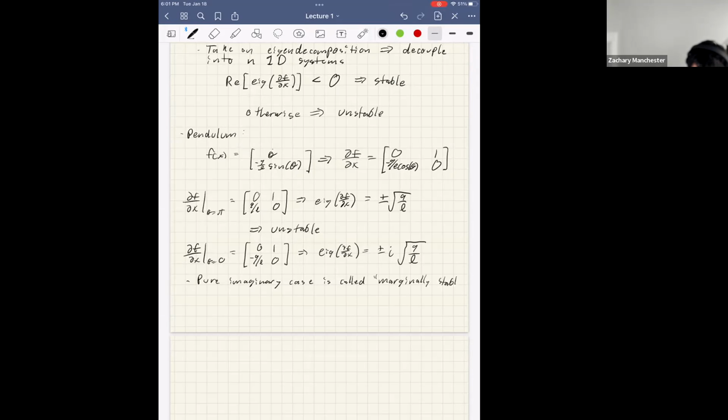This is true in the linear systems case, but if we're applying this linear analysis to a nonlinear system, what this means is that there's going to be higher order terms in the Taylor expansion that we're ignoring right here. If these eigenvalues have 0 real part, you can have these oscillations, but you've got the nonlinear terms in there too, and all bets are off on those.